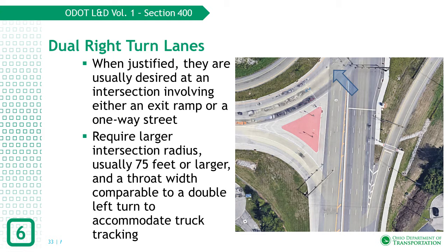In these situations, the first step would likely be to see if the right turn on red can be permitted. If it can, and it still leaves the right turn over capacity, then a dual right turn lane could be implemented, recognizing that only the outside lane would allow the right turn on red, and drivers would want to utilize the outside lane nearly exclusively. The inside right turn lane could offer enough utilization to allow the right turn to function acceptably.